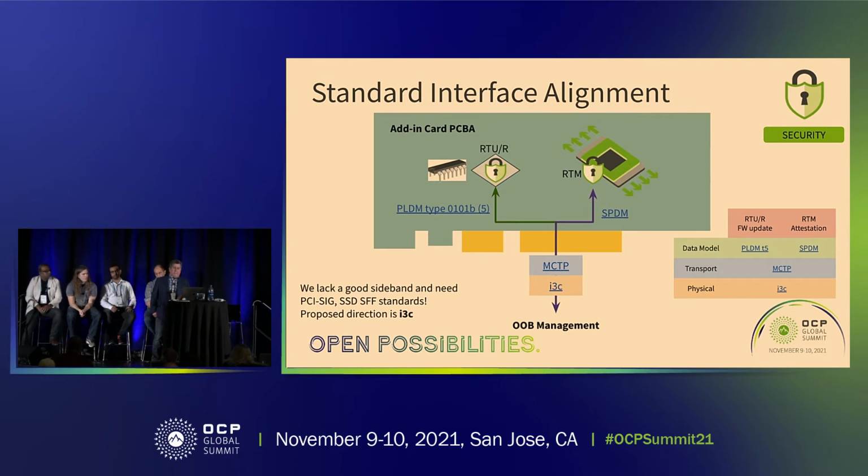So for the RTU, the root of trust for recovery, we're proposing that the interactions are going to be through PLDM. And for the RTM, which is the root of trust that guarantees things like secure boot, and a lot of other important information specific to the environment that you're running, we are proposing SPDM, meaning any root of trust that is available out there that is doing RTM type of work should be able to respond to SPDM commands, and the way to communicate with it is through SPDM.